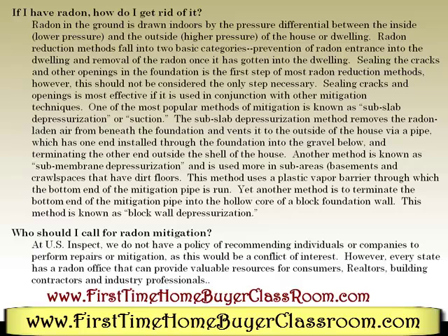One of the most popular methods of mitigation is known as subslab depressurization, or suction. The subslab depressurization method removes the radon-laden air from beneath the foundation and vents it to the outside of the house via a pipe, which has one end installed through the foundation into the gravel below and terminating the other end outside of the shell of the house.